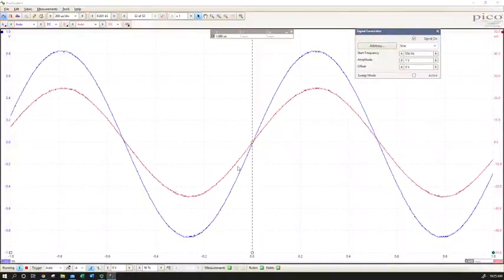If we use our formula for resonance, which says F resonance is 1 over 2 pi times the square root of LC, so 2 pi times the square root of LC is all together in the denominator, equaling F resonance, we can put in 950 for F resonance.